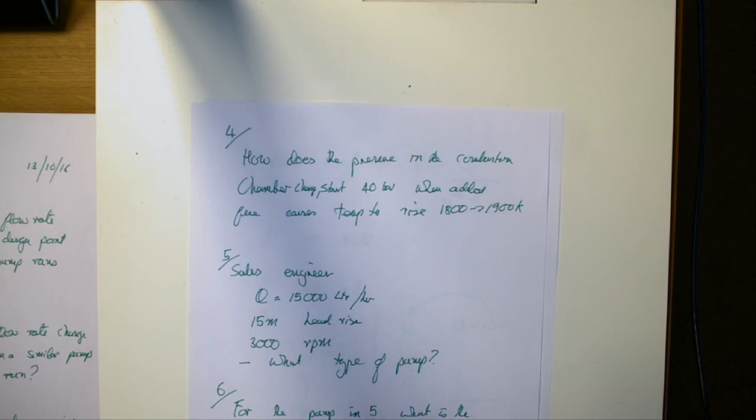Instantaneously, the engine cannot change rotational speed. It's just sitting there. It's got inertia, you know. It's a rotating mass of some hundreds of kilograms. It's not going to change speed instantaneously. But the pressure and temperature inside the combustion chamber immediately respond. Now, my question is, how much?